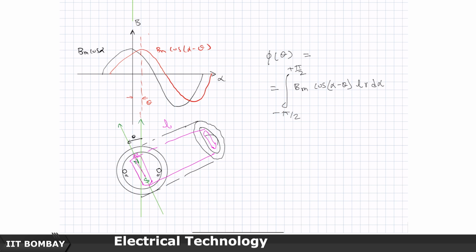distance here, and the arc that is created is d theta. So, this is actually r d theta, and it has a depth of L, and so L r d theta is your ds. We have seen this. So, what we are now going to do is we are trying to see when the magnet has moved by an angle theta, what is the flux linking the coil A dash, and we have come to that it is going to be this particular value.